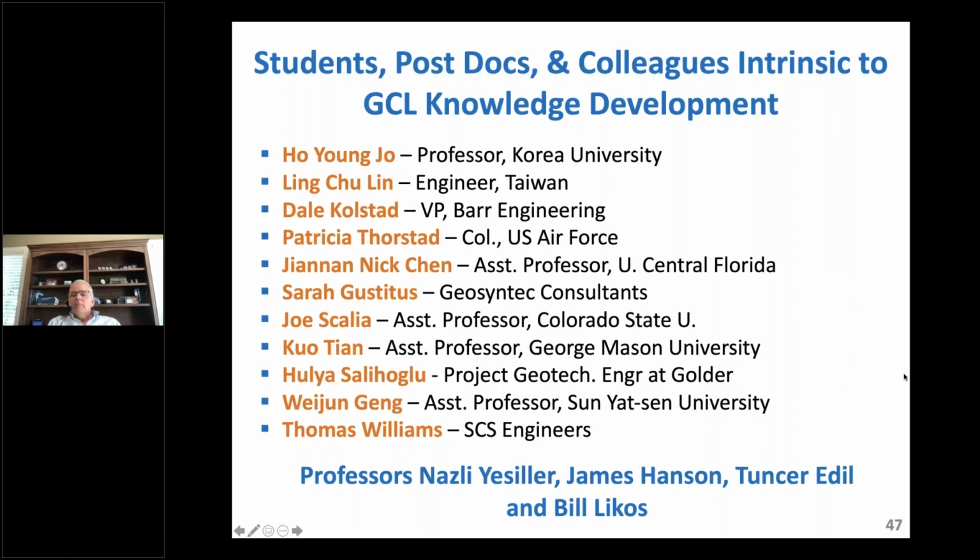From Spencer Harvey, here's a little longer. I've got to open up my chat box a little more. Would you expect calcium exchange on GCL placed directly on a soil rich with cemented calcium carbonate in an arid region, less than 20% of precipitation on average? The GCL is part of a composite liner with active leachate collection system. Yeah, if you put a GCL on top of a calcium rich subgrade, you will get exchange. And if that subgrade is not moist enough, you will probably exchange it with calcium before it fully hydrates in a sodic environment. I've run into this.